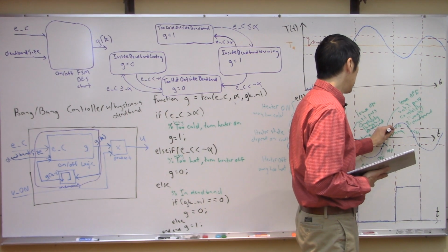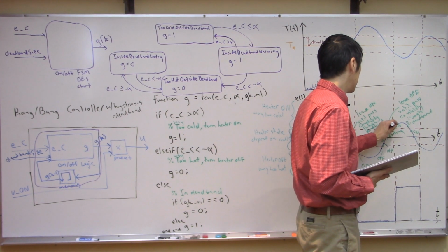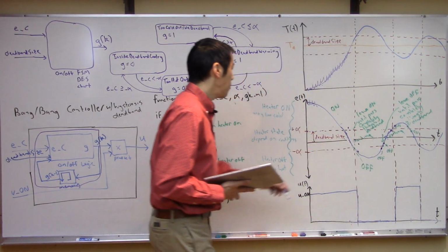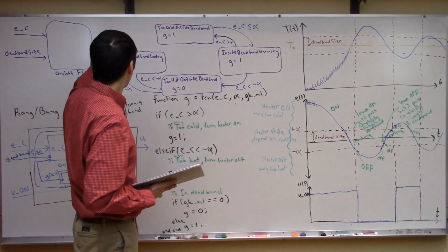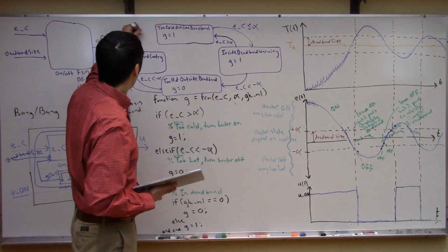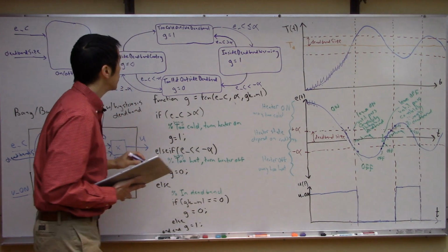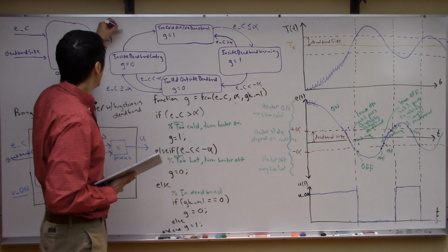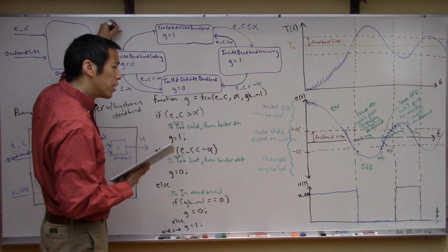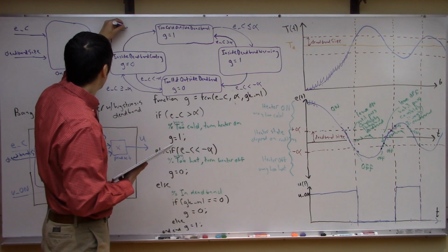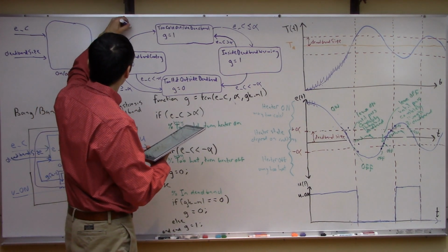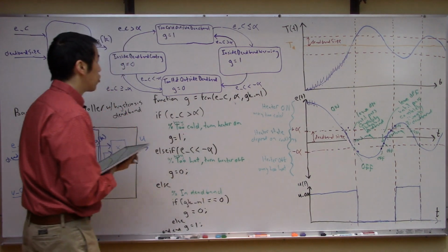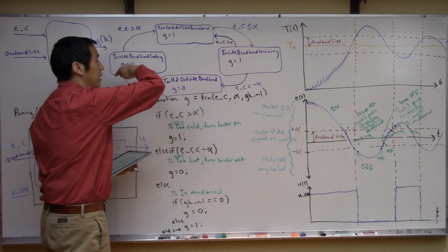Now the second that you go from here to here, that's when we flip to the on state, right? So that means we go from here inside the deadband to cooling, and we go over here, right? To being way too cold and you're outside of the deadband. This occurs, right, when your error signal, right, is greater than alpha. Right? That's when you leave. So you can see around and around this finite state machine we go.